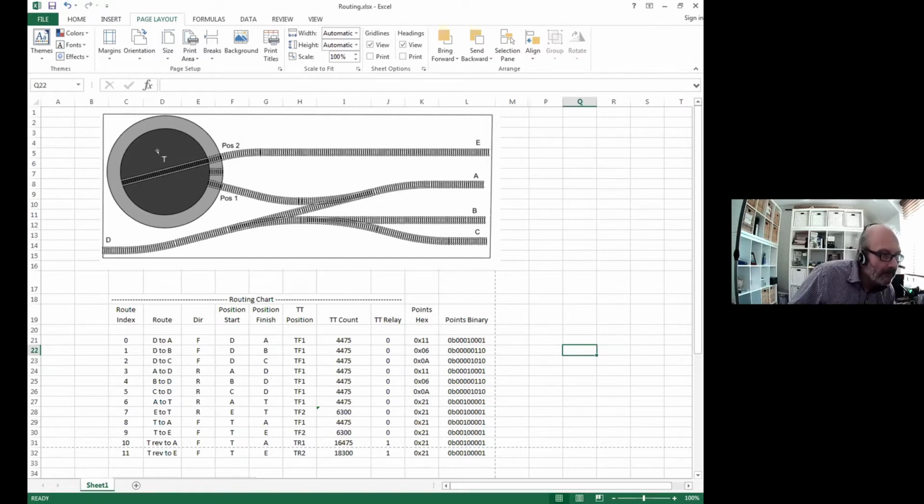But what I'm thinking of, particularly in this application, it's not a generic solution, is putting a laser sensor across here. Hopefully I might be able to use one laser for both positions. So as it comes on, it will cut the laser, and then I can say, right, it's on the turntable, I can now move on. But it's only this particular application that it will work for.